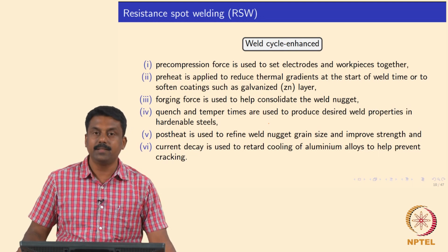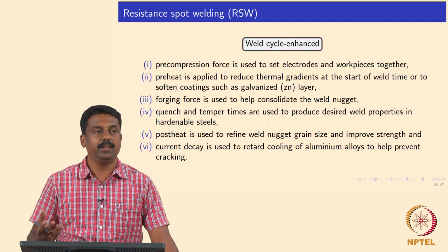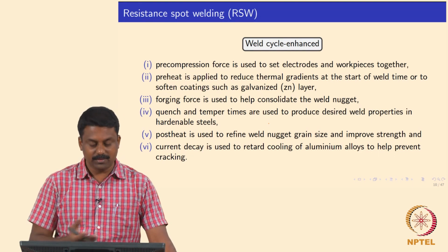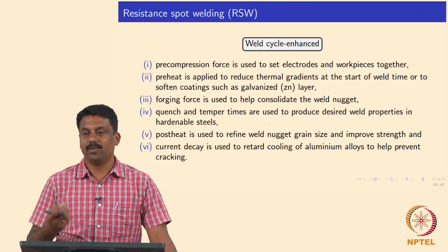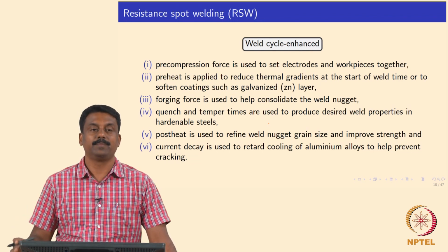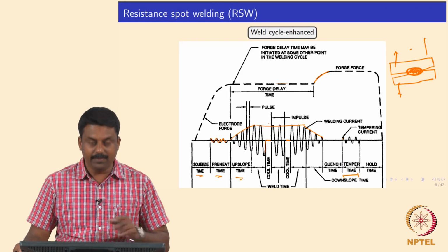Good. Any questions on this? It's extremely important to understand this, because when you are doing resistance spot welding at industry scale, these terms are quite common. Squeeze time, for example, post pulse time, number of pulses. So we always tell the welding time in terms of cycles.